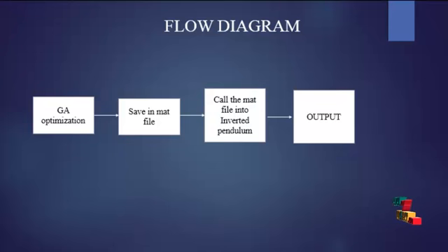While constructing a linear servo system using a sinusoidal reference input generated from the pendulum trajectory, this control method is based on state space pole placement design techniques using the linearized model of the inverted pendulum. This implies that the stabilization control by itself will only ensure local stability at the upper equilibrium point, the point about which the model was linearized. The pole placement technique permits the design of a linear controller.